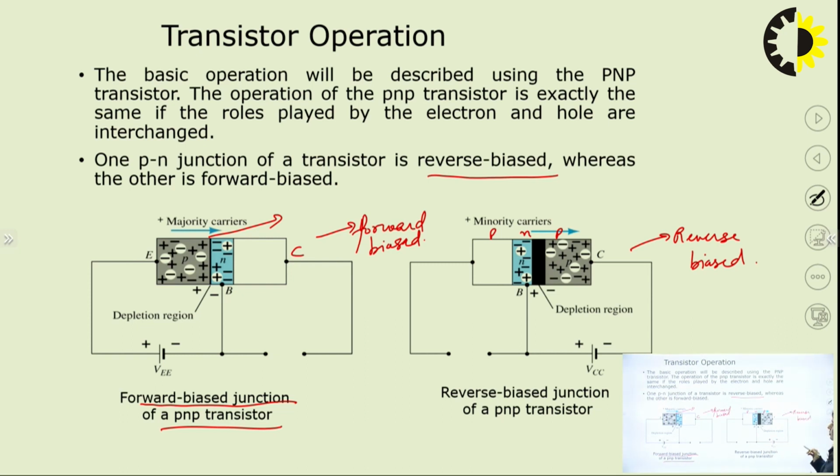So we have forward biased in the emitter base junction and reverse biased in the base and collector junction. So we have both the emitter current and the base current in the forward junction, and similarly we have a minor current, in microamperes, at the collector side. These two diagrams depict how you can forward bias or reverse bias a PNP transistor. The thing you have to see is that the emitter base junction should be forward biased and the base collector junction should be reverse biased. So one PN junction is forward biased and one PN junction is reverse biased here.